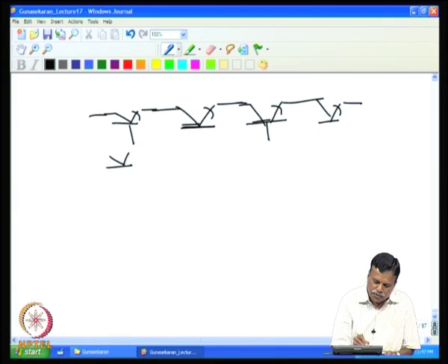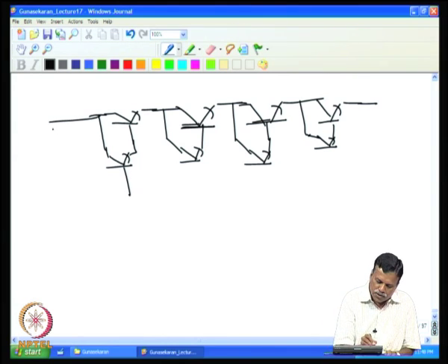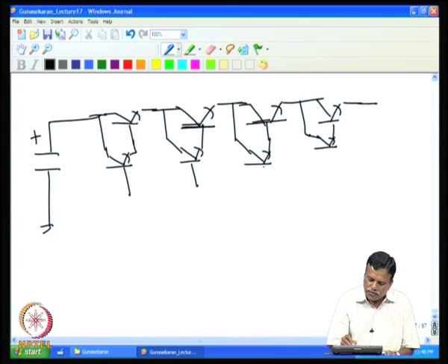Now, when I put transistors, I put them in Darlington also, so that the base current becomes small. Each one is only 300 volt. So, I connect each one in Darlington and get the output. This is our unregulated DC here. So, you have a negligible base current, and if you need, we can put one more Darlington also if you want to reduce the base current here. Essentially, we have to have a Darlington pair arrangement such that the base current is negligible. This is essential for this design to be successful.